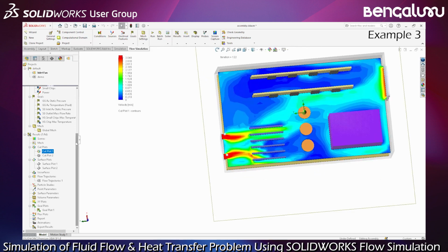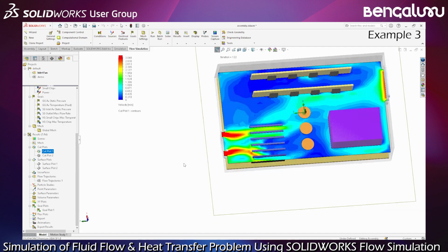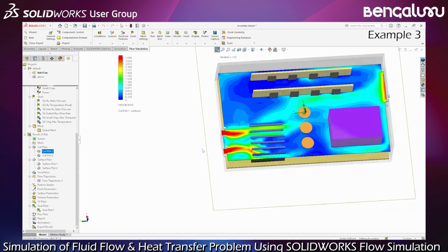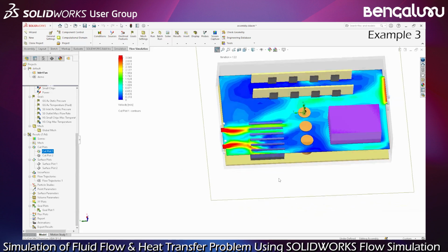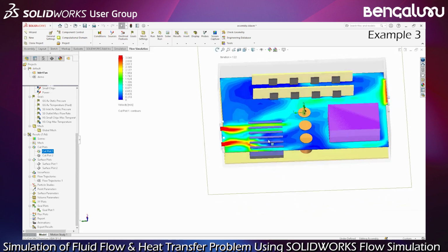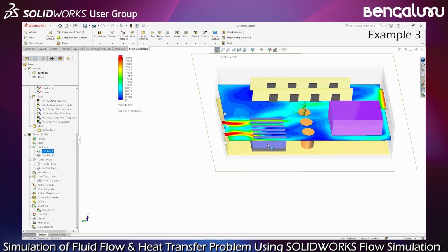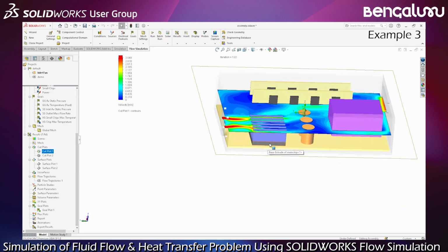Again, my conditions are pressure here and the external fan, with inlet conditions via the enclosure. Just from this result, I can say it's good to have the fan in front of the heatsink so that I will get a better cooling of this component, which is the main chip.